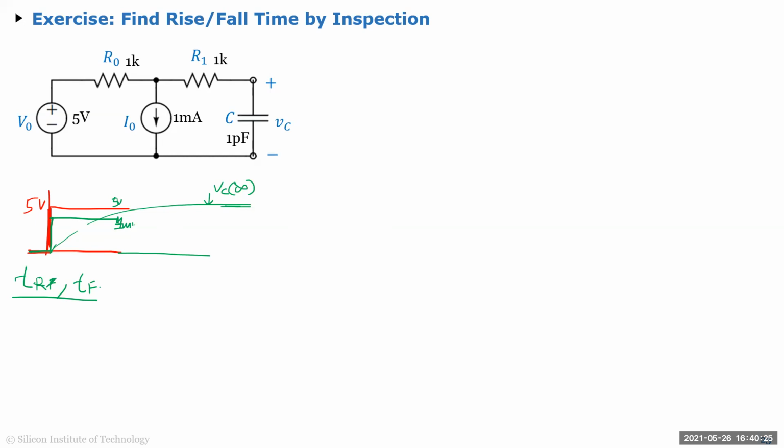So, firstly, I take that Thevenin transformation. The source voltage I am getting is 4 volt, with a resistor of 2 kilo ohm in series. Basically, when we are calculating for steady state, the source voltage will be the same as the capacitor voltage, I guess. So that's why at steady state it will be 4 volt.